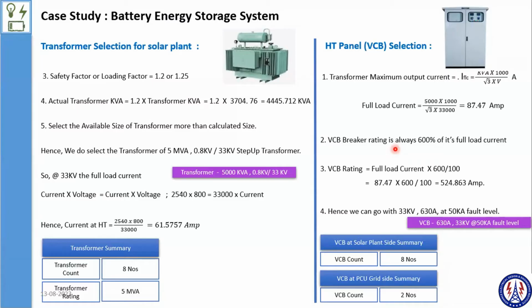And this 600 comes because it's on a low ampere and there is no switchgear available on the lower side, and that's why it comes to 630. So if the current rating is lower than, let's say, 100, like 15 amps or 16 amps or maybe 50 amps, then if you choose 630, it goes to 6 times more than that. That's the scenario.